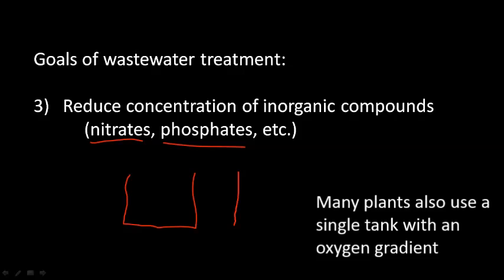Each tank will end up containing a different type of bacteria depending on the oxygen preference of the bacteria. The preliminary tanks are oxic. They contain a large amount of oxygen, and the purpose of that is to oxidize, or nitrify, nitrogenous compounds like ammonia. Then we have progressively less oxic, or oxygen-deprived, tanks, which create a reducing environment.